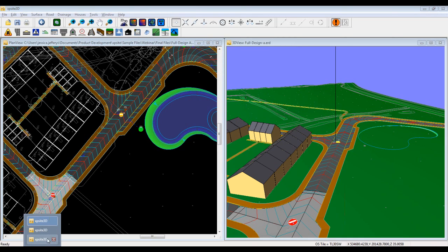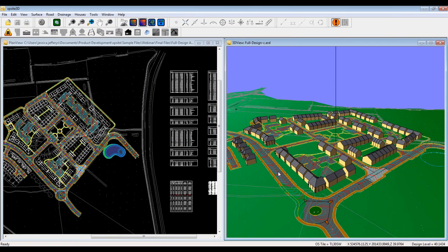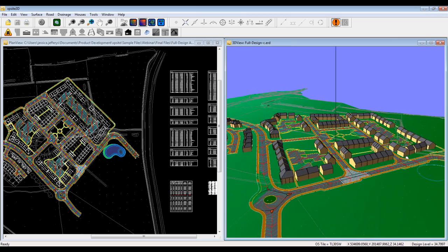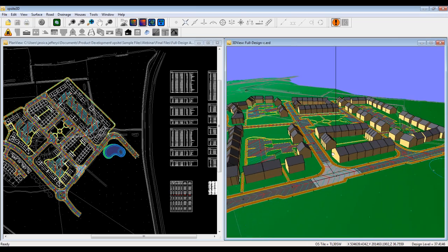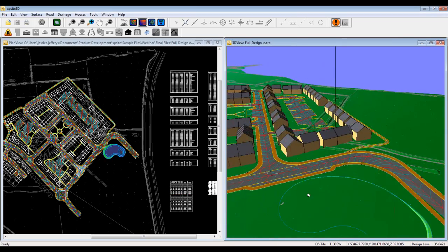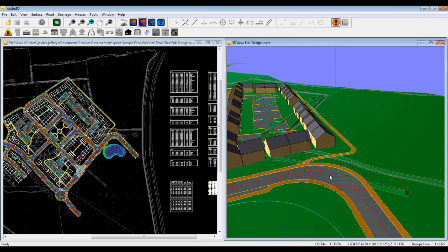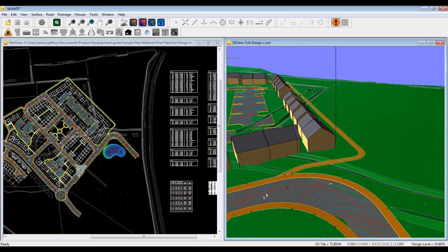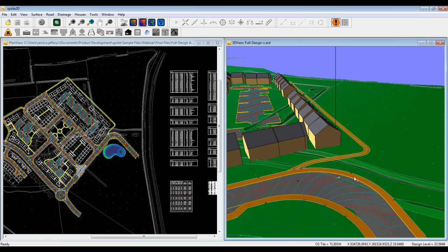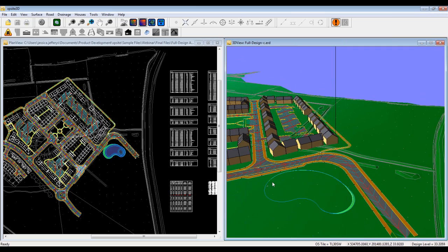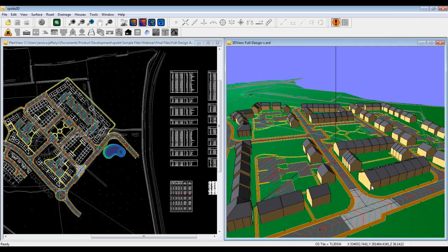So if we move finally back to our finished design, we've only been able to show you a few of those channel tools, but if we zoom in to the 3D view here, we've seen the speed bump already. Around this corner we've actually got some vertical changes to the profile, which you can see with the contours to make sure that's appropriate for driving on. So that's been added in there.